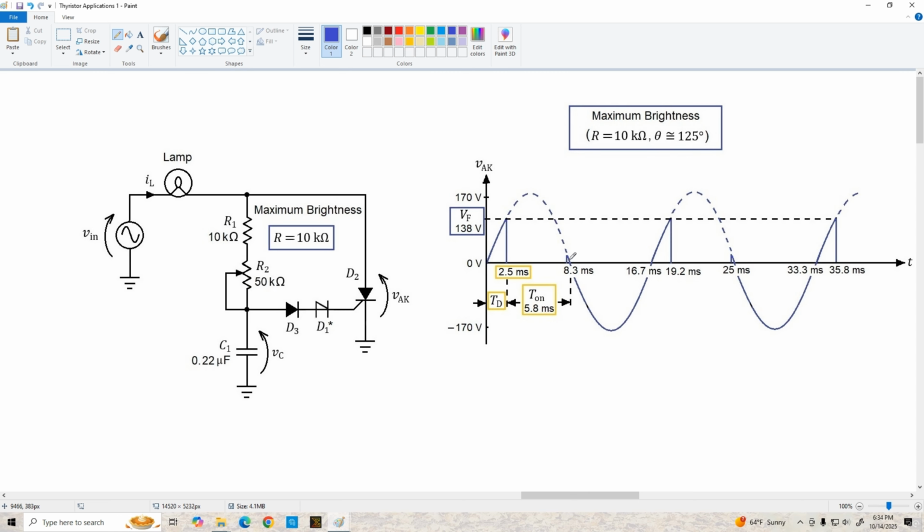Now, the SCR turns off, and for this next half cycle, the line voltage is dropped across the SCR, and we get this entire negative going portion of the waveform, and that continues until we trigger the 4-layer diode again, and this just repeats over and over again.